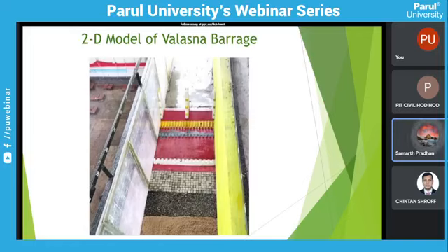See, this is our flume. This is our acrylic sheet, from which, through this observation chamber, we can look at the water pattern. So we can see the height of the jump, the pre-jump and post-jump, where it is starting and where it is completing. That you can study.